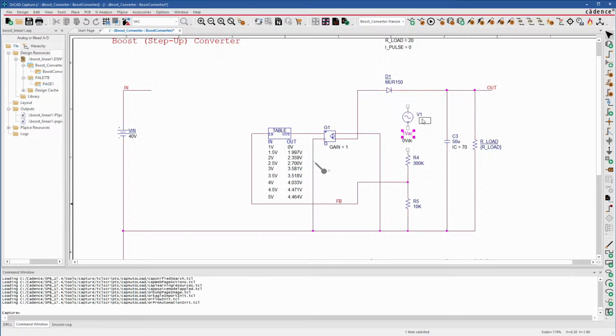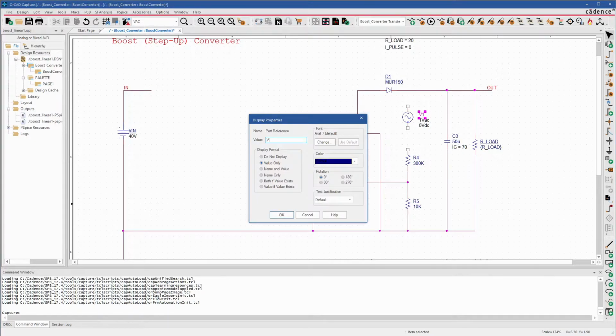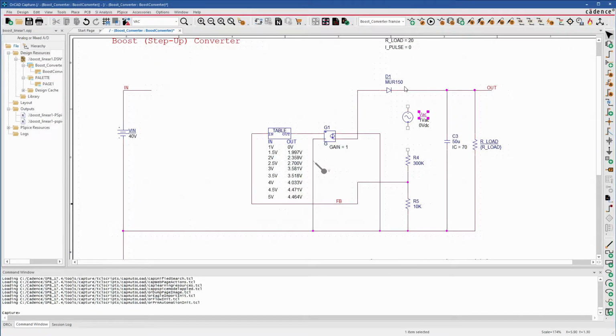So we'll just put it this direction with the positive facing down. And I'm going to rename this VAC. W for wire. Now that we have this in here, we need these nodes to be named. So we'll call this feedback, and this one we'll change to feedback 2.